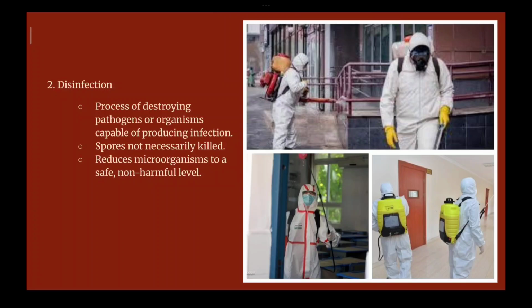Keeping the good microorganisms is also essential in the surroundings because they are helpful for the biosystem to be balanced. So it is essential to keep the microorganisms in spore formation, not exactly in the vegetative form. So disinfection is used in destroying the vegetative forms. There is a difference between disinfection and sterilization, and that is essential to know.